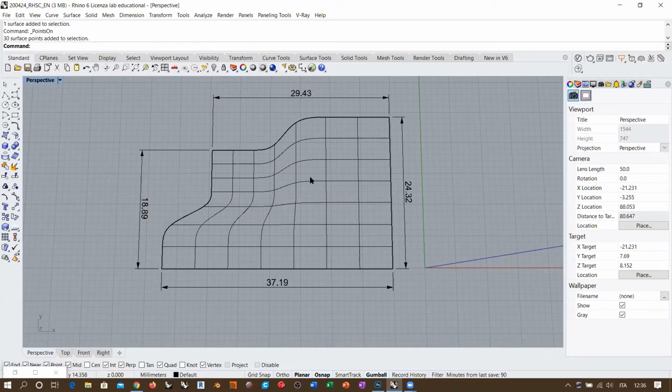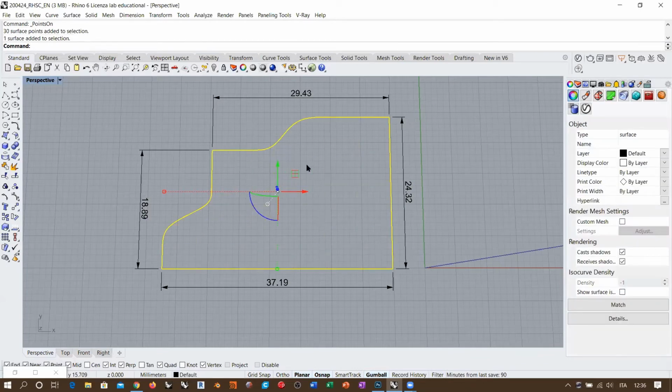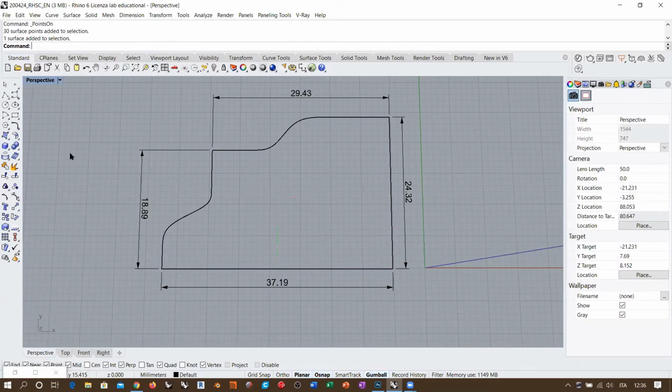And this is the reason why, if I, for example, don't consider the actual visible knot lines, and take an extract isocurve command for this surface, you see that the left side is moving slower in this area, and then it starts to move at the same velocity, okay? Therefore, you have this deformation. And as well, if you toggle the direction, you will have this deformation occurring because this area is slower than this area here at the bottom, okay?